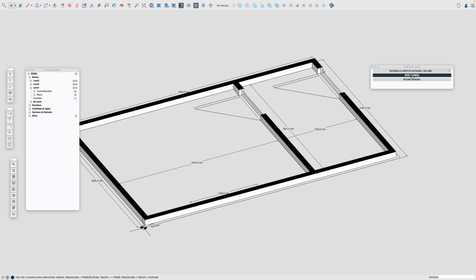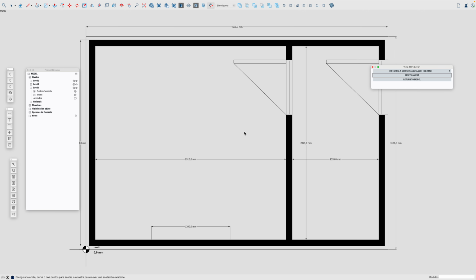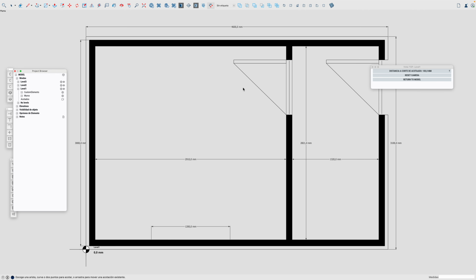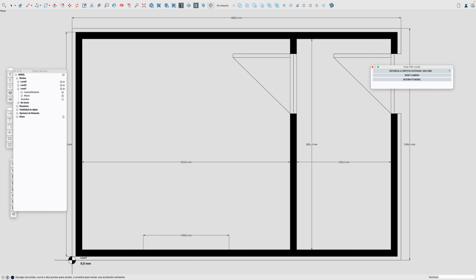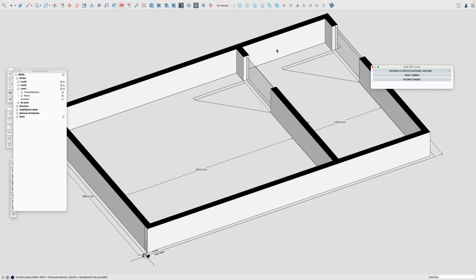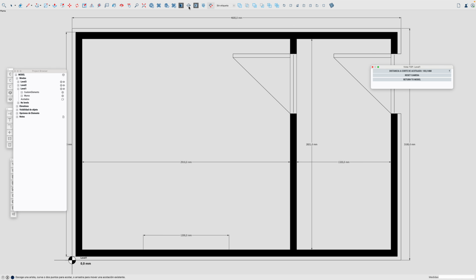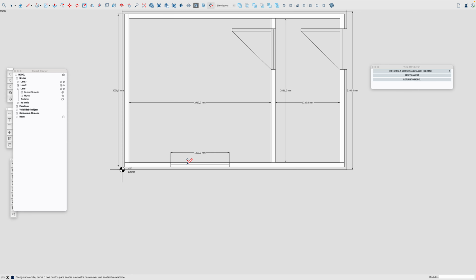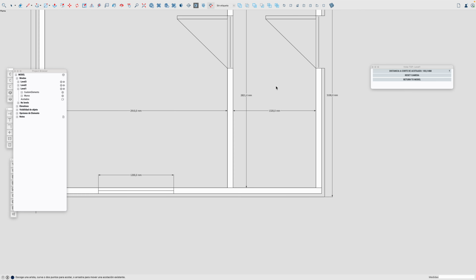One is the reset camera, which positions the camera again so you can place the dimensions again, and you can edit the distance of the cut. I can choose like 400 millimeters. So from the level position, the cut will be 400 millimeters. The fold is 100 millimeters, and it's enough to show you everything you need to see to place dimensions.